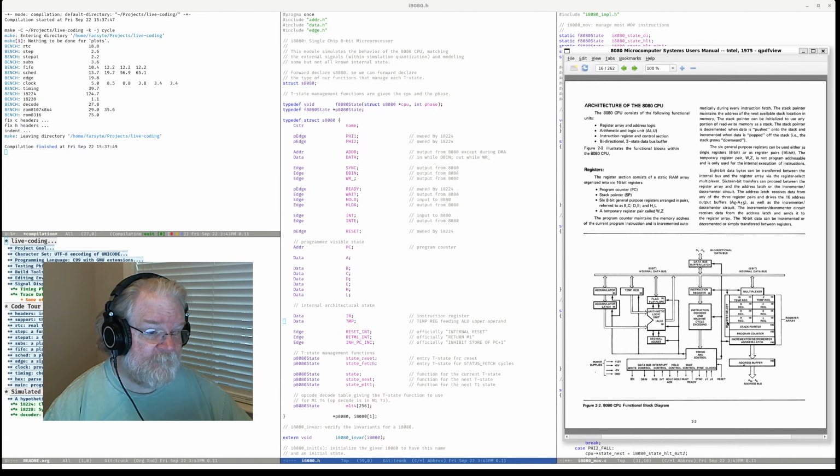In T4, we select the register, and it goes out onto the data bus and latches into temp reg. Then the ALU has a chance to chunk on it, and the timing control is set to say, just let this value through. So the data we read is now latched here and produced, and then during T5, we are going to either latch into the accumulator or into one of these registers.